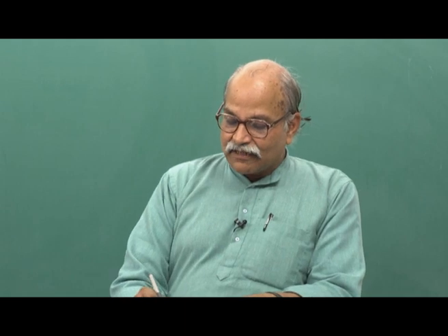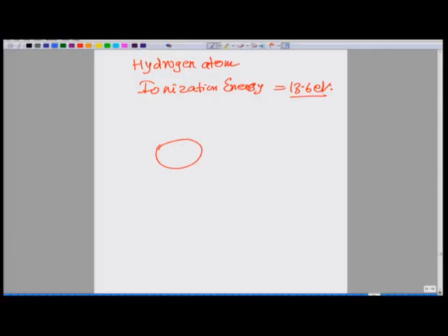Similar modeling you can do here. You have that impurity atom, and this impurity atom has some charges, and this fifth electron is outside, and this has a charge plus e. So, you can try doing this modeling. So, how does that 13.6 eV come? If you look at the expression, that is given by the mass of the electron times electronic charge to the power 4, over 4 pi epsilon naught whole square and n square h cross square, n is 1. So, this gives me the energy.